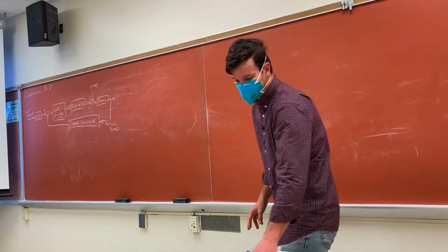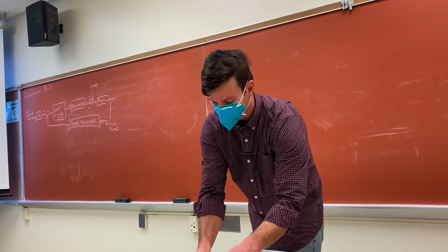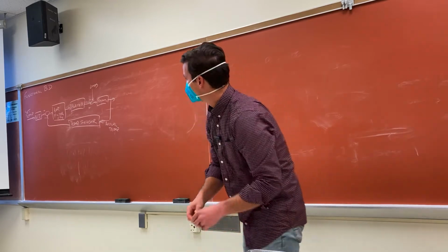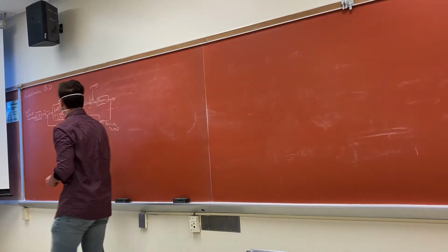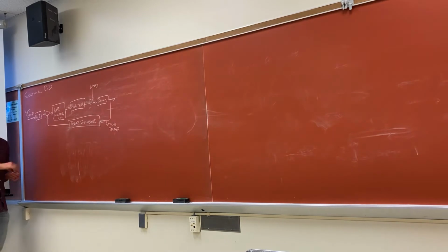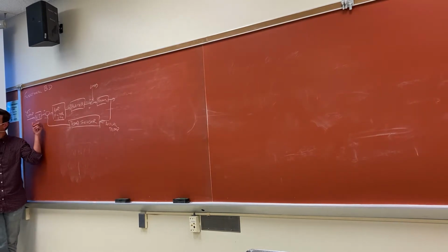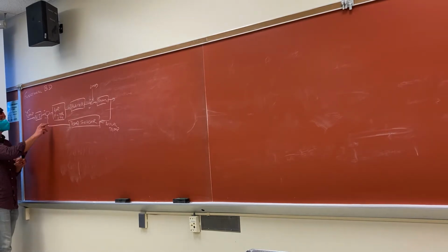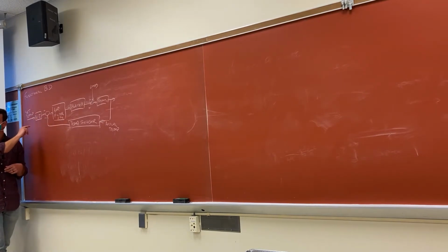Something to check when you're drawing your block diagrams, whether they be Laplace or functional or whatever, is that when you go to add or subtract signals, these two signals have to be the same units. All right, so that's a double check for you. Whatever units this has to match, or else this addition won't make sense.